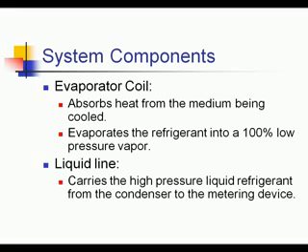So in this example, I have my metering device. We have 278 psi in front of the metering device on the left side, and it's pure liquid. On the right-hand side, we have dropped the pressure through the metering device to 70 psi. We now have a combination of liquid and vapor, which is known as flash gas: 75% liquid, 25% vapor.